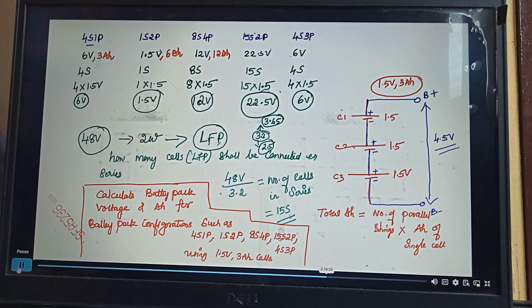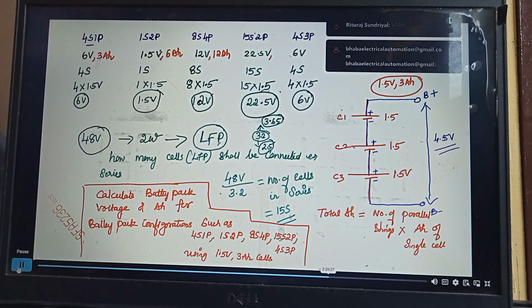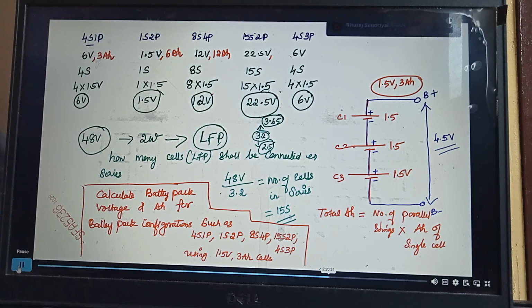Yeah, LFP nominal voltage is 3.2 volt only. Okay, tell me for 15s2p, what is the Ah? Yeah, 6 Ah, very good.